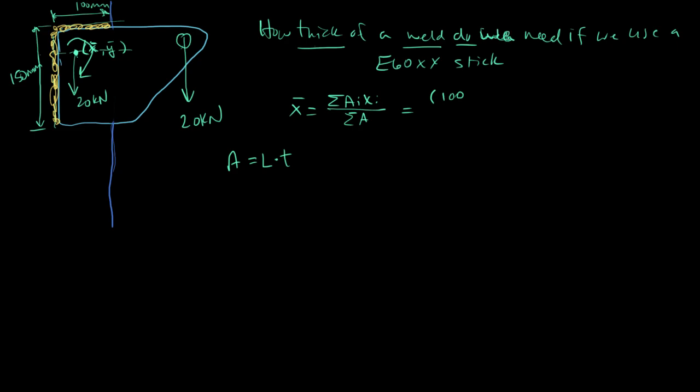And we know that if we have a symmetric weld, the throat of the weld is 0.707 times the leg of the weld, and the leg of the weld is how thick the weld is, or the height of the weld. So that's your H, and then this distance here is your thickness, right? We're trying to find that information, so we'll just leave that as a variable.